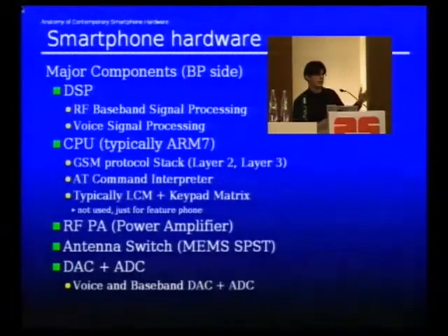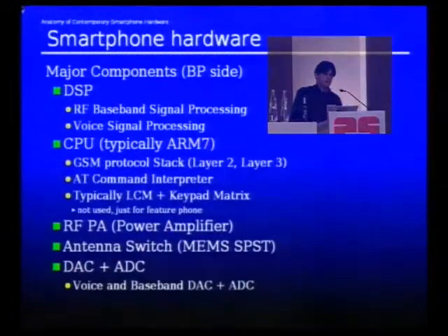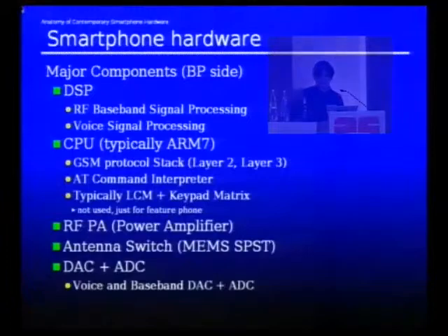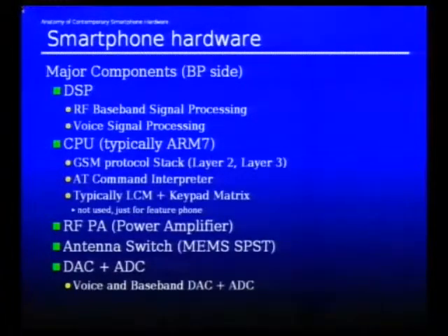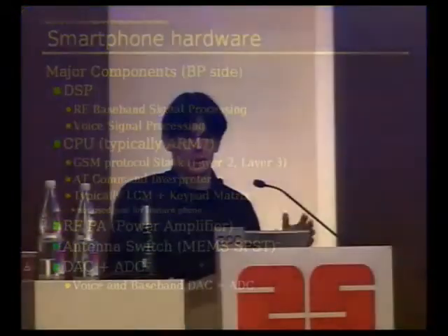Now with the higher end 3G, 3.5G modems, it's ARM9. And that CPU only runs the GSM protocol stack and typically an AT command interpreter for an AT command modem interface. You also have LCM, which is a LCD screen module, and a keypad matrix interface, which is not used in the smartphones because the keyboard, if there is any, or the keypad, as well as the screen are connected to the application